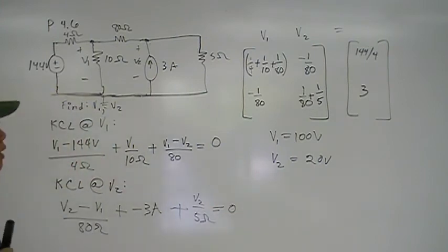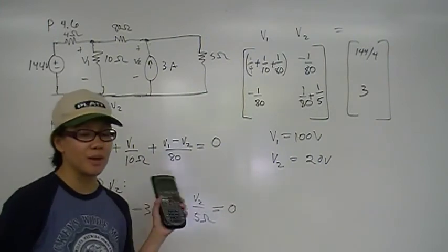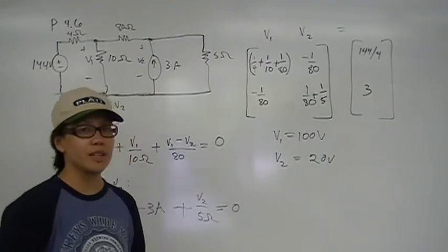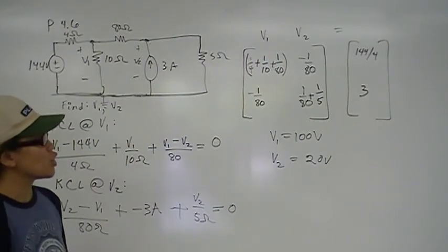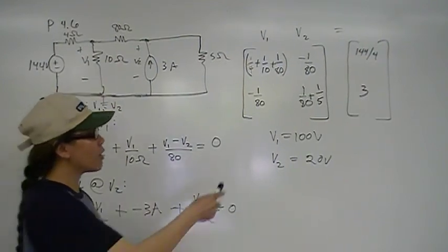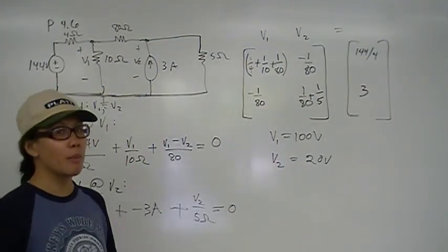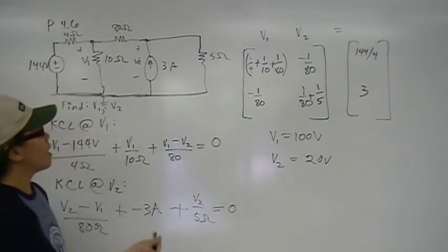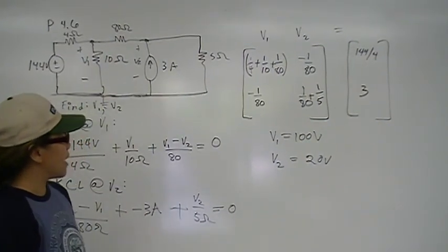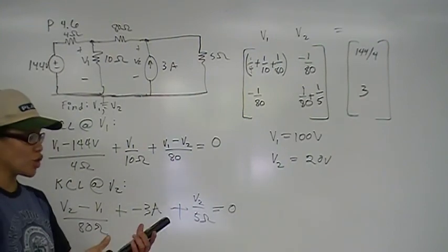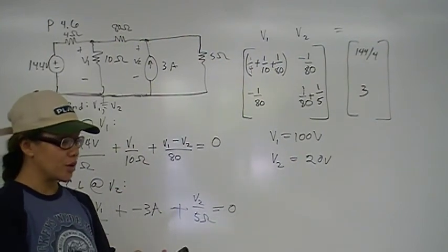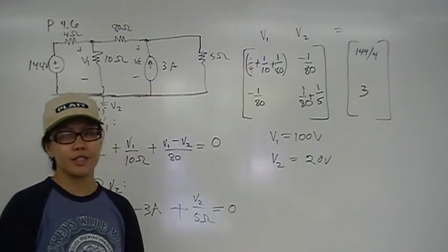The issue that I had was not that the setup of the equations was wrong. The issue was with my simultaneous equation solver. It's very easy to make mistakes when you're entering fractions, and that's what I did. As far as troubleshooting goes, if you have symmetry across the diagonal, you're looking pretty good. If you don't, then double check your signs. You've probably done something like adding a branch current going into a node. Also, you might fat finger entering the fractions, so be very careful when entering them, because it's easy to enter them wrong.